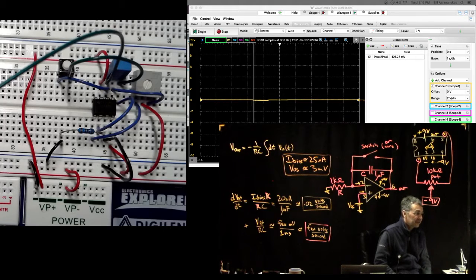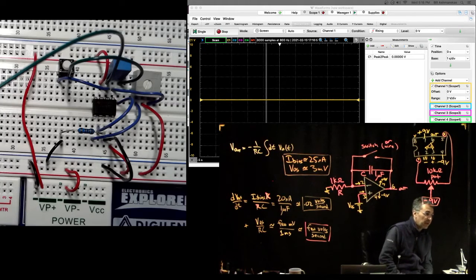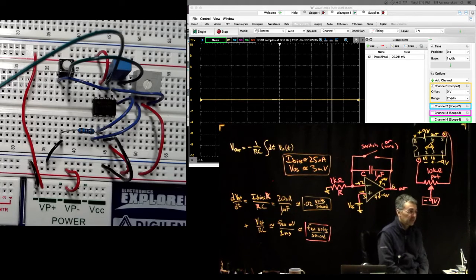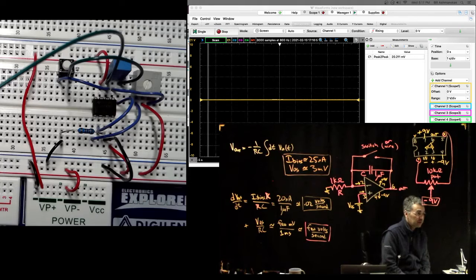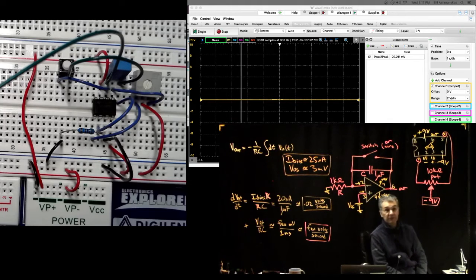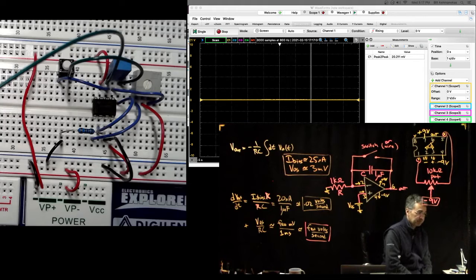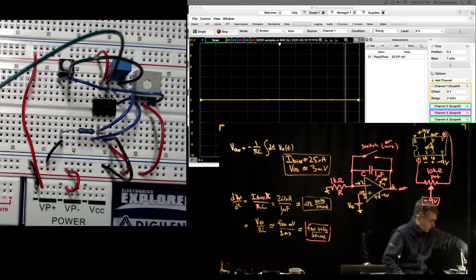of course, I still have the I bias effect, so I might have been off by like 1% or so in how much I zeroed V offset, because I might have overcompensated a little to take out the I bias effect. But remember, we saw that the I bias effect was about 1%, like 2 orders of magnitude smaller than the V offset effect. So this is pretty much just zeroing V offset. That's a useful trick to know.